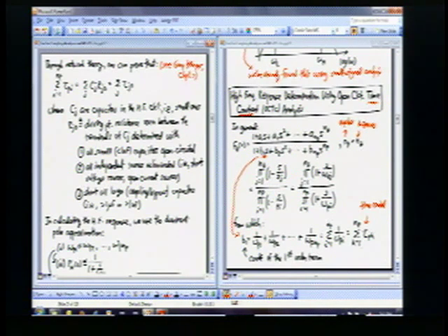Yes? So if fh of s is the frequency shaping function, then why is it that the magnitude goes down when you get close to a pole? Because wouldn't that mean that it would be going up? Well, what happens is when you get to a pole, so look at this right here. If s gets larger than omega pi, then suddenly this term becomes greater than 1. And it's a term in a numerator that's getting larger, and so the whole thing gets smaller. Yeah, so the math does work out for that.